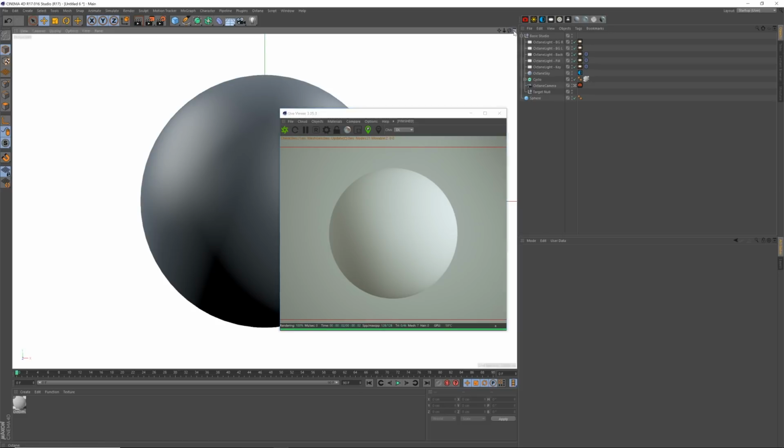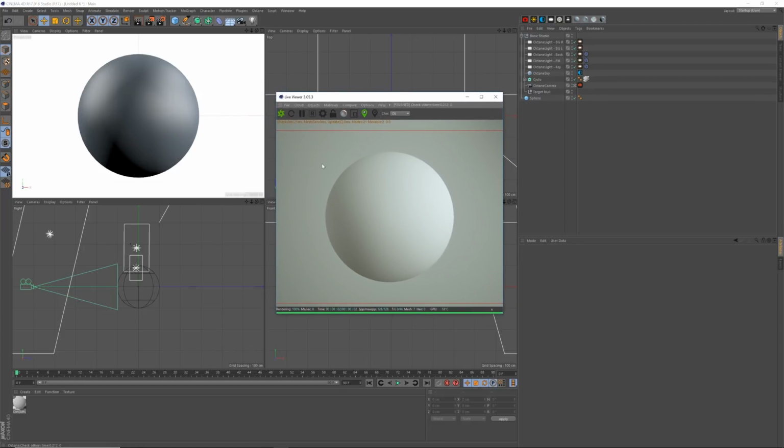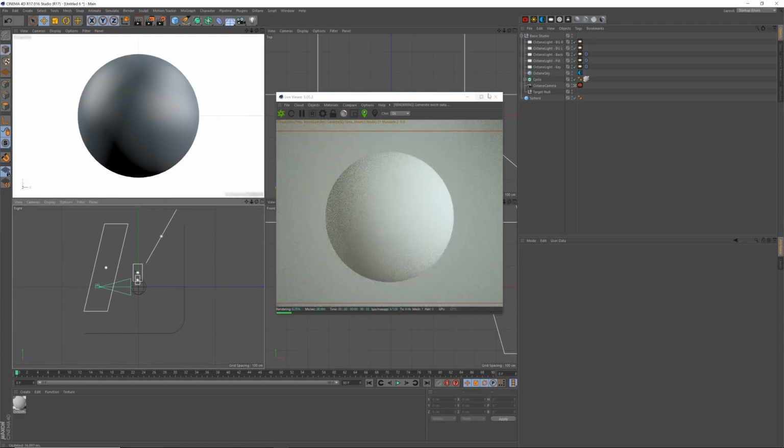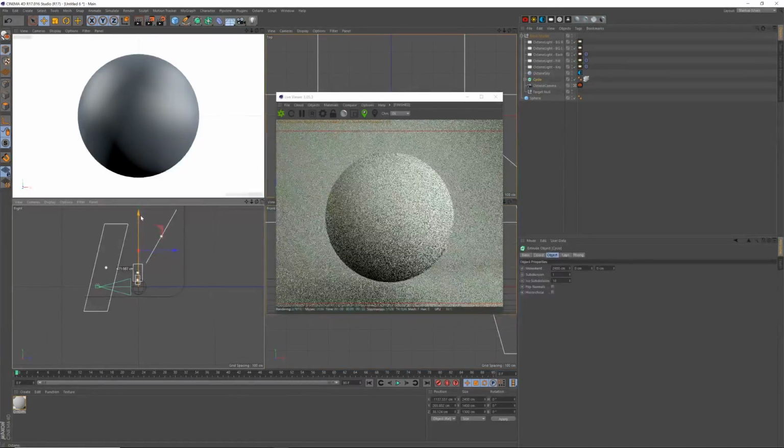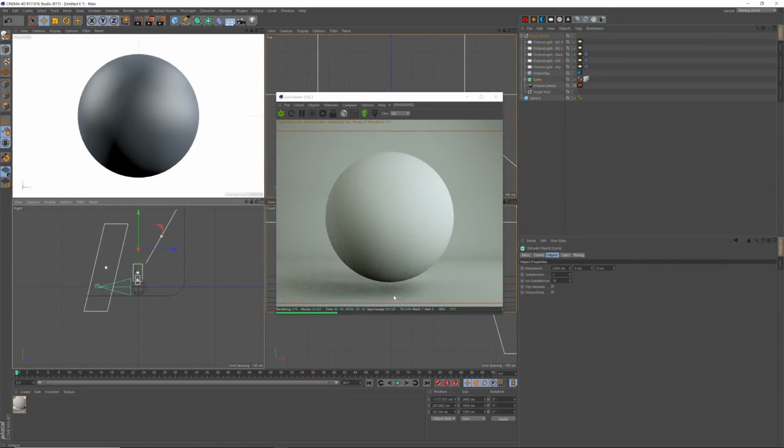What I like about this setup is, if I zoom out here, I've got a flat background, well lit, but I've got lots of options. So if I want a shadow underneath, I just select the cyclorama, make sure I've got my model and position tools selected, and I just drag it up, and then I've got a floor with nice shadows.